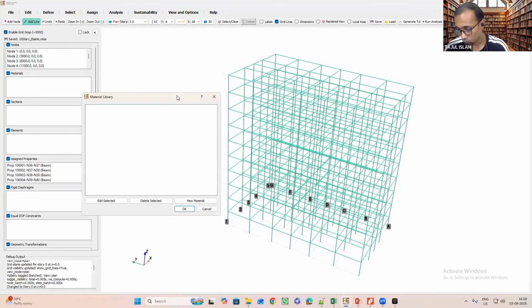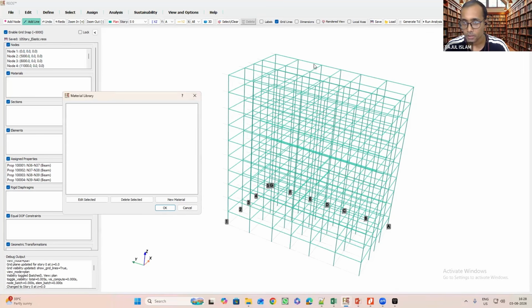We'll do it soon. So if you're thinking of using the fiber section modeling for the elastic model, then it will be available soon. It's not a task like we cannot actually, we just forgot to implement this one. Okay, so it will be done soon. Now what we'll do, we'll model the beam members using elastic beam column as well as the column members for the elastic model. Okay. Then when we are modeling the nonlinear members, then we'll replace the elastic member for columns using the fiber sections. Okay.